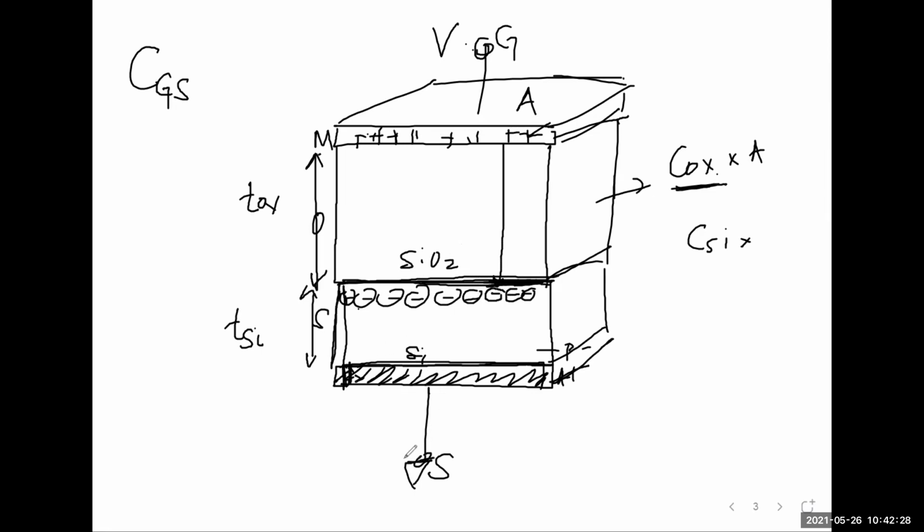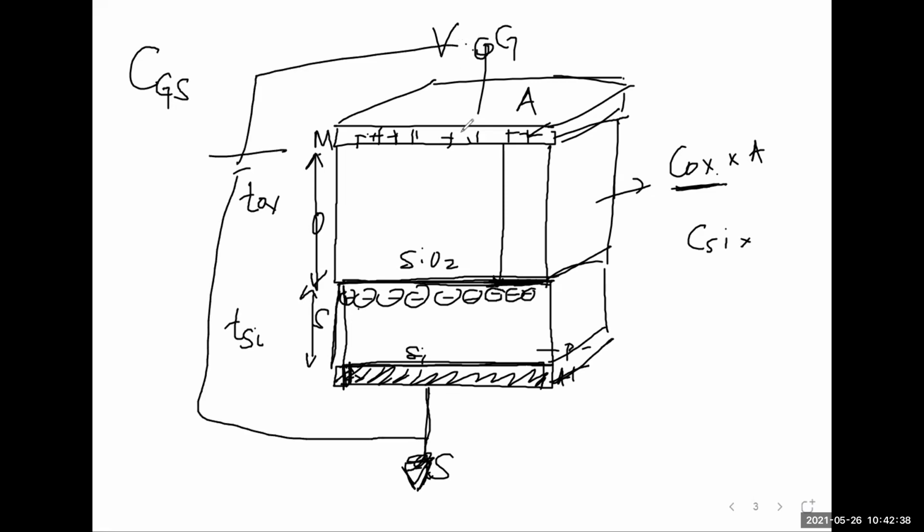But now because there is a path to your battery terminal, the holes will just go away and get eaten away by this battery basically. So you're putting a battery across, right? So whatever charge you're coming here, it'll just flow through the circuit and come back here, right? So you have a circuit to complete now. Now, because I said P minus, this layer is not going to be very thin. So it is going to be like this. Now, what should be the capacitance from G to S now, knowing this?